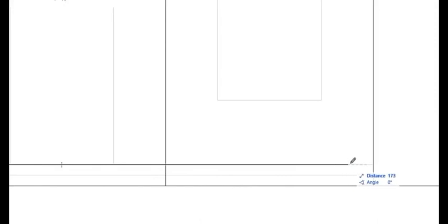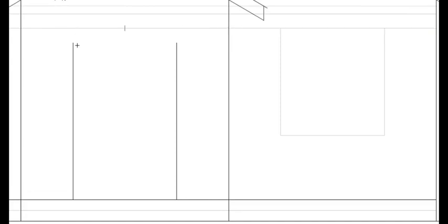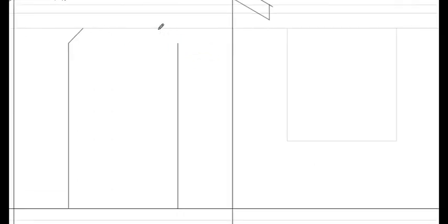That is our slab. Our opening. Now with an arch, you basically measure 4 millimeters from the top, then draw an arch at 45-degree angle, and also do the same for this other side. Then just join this to this.